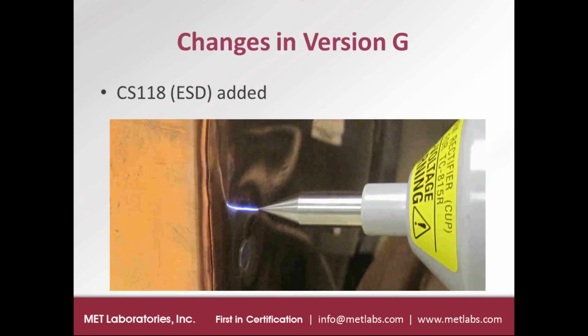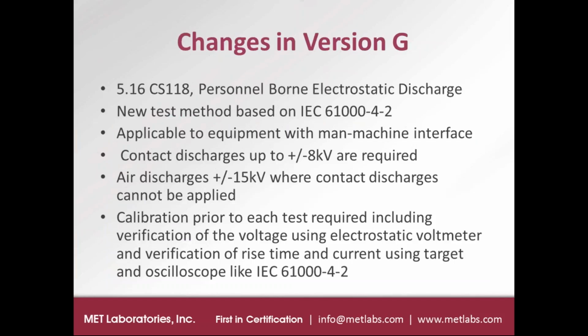Another test that was added to version G is CS118, and that's electrostatic discharge, ESD. CS118 is based on IEC 61000-4-2, which is an international standard for performing ESD testing on electronic equipment. It's been around for a long time.